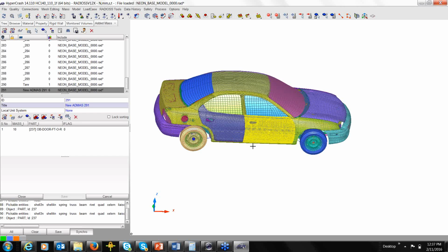But what happens with capturing all the element size is the turnaround time, the result. When can I get the result back? Otherwise, the best approximation is to capture everything, have the smaller size element, but you need a huge machine. You need a bigger, powerful machine to run this job so you can get the result overnight. But if you don't have a powerful machine, then you need to make your element larger so that you can get the result sooner.